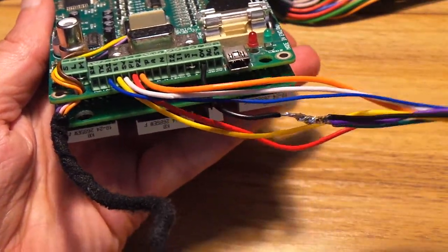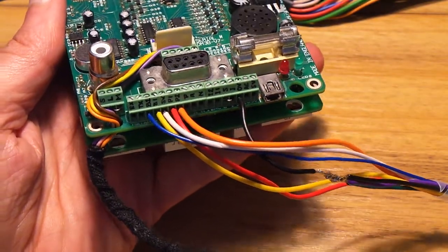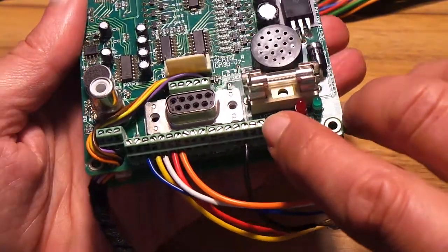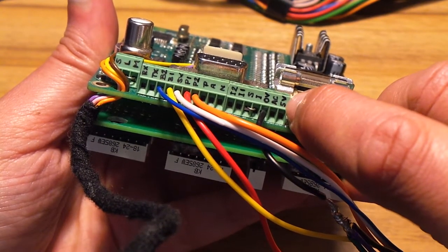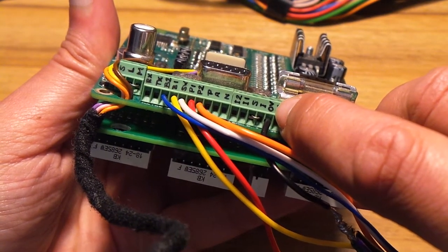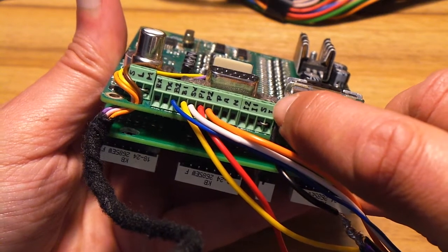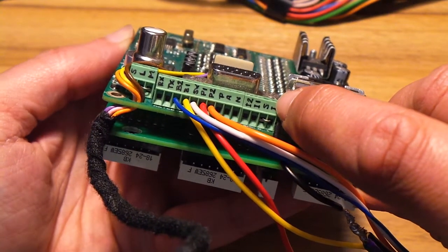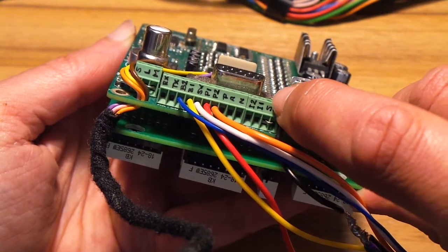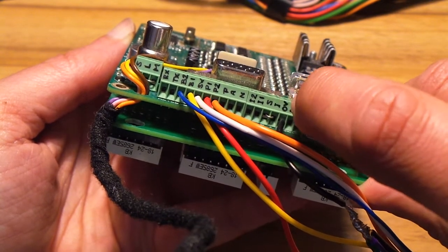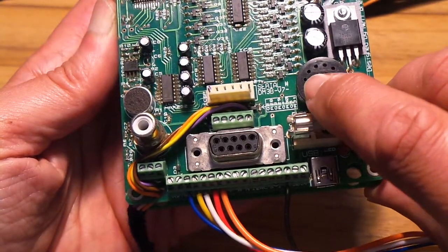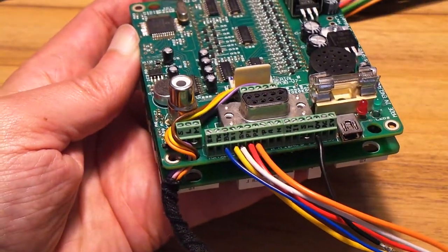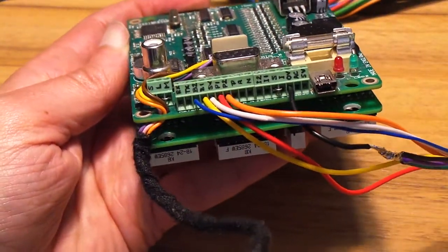The ground connection from this box is going to go in on this pin marked 0 volts, so that's the third one from the right. You can see that we have a small wire link between these pins marked S and I. S is the speaker drive out and I is the internal speaker, so if we want to use this internal speaker we need a small wire link between those two pins.